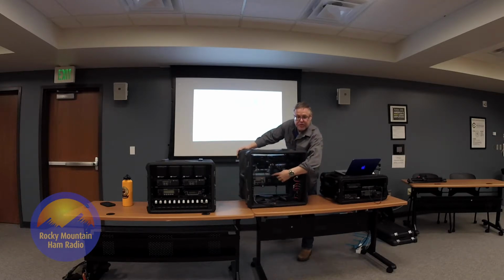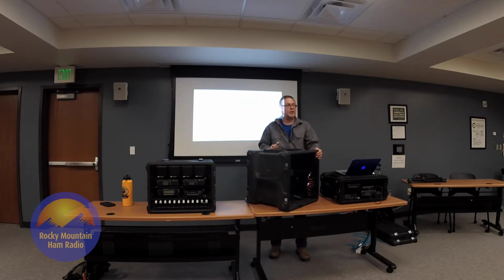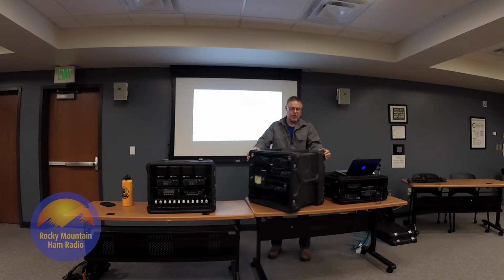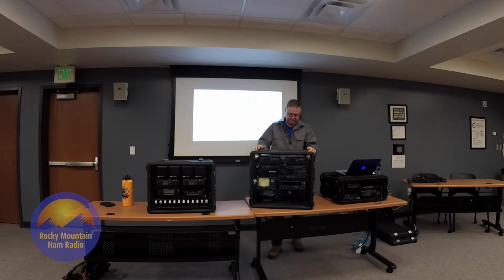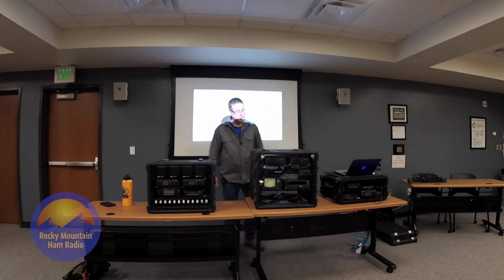This USB to serial adapter to control the radio, make sure you screw them in. They will bounce out the first time you transport the vehicle. Transport the PODCOMM. I can't stress it enough. Make sure all your antenna connectors are tight.